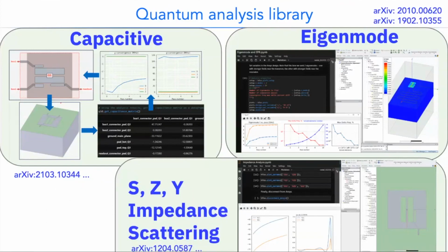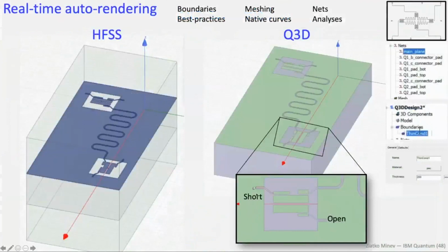Maybe Thomas will even talk about it next time. But basically, with Metal, you can define ports, like a drive port, just ports for simulation. So you can see if I put a voltage at this frequency at this power here, how much leaks through over here. So that's why it's very important to have these open and short terminations.